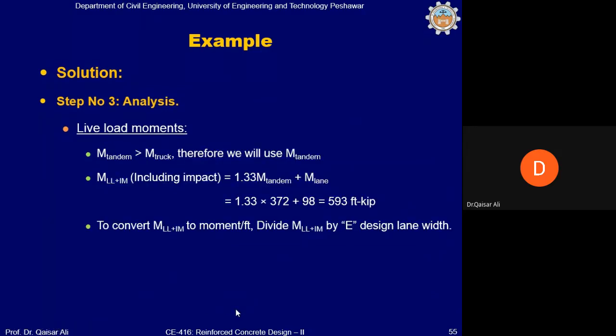We will take the maximum bending moment for the two vehicles, which is coming from the tandem. So we will use tandem bending moments instead of truck bending moments. And we will also apply a 1.33 factor to the tandem bending moments in order to include the effect of vibration or impact. So 1.33 into M tandem, 372, plus M lane, 98, gives us 593 foot kip, but for line moments. This must be divided now by E to convert this bending moment of the line to two-dimensional, in order to include the two-dimensional effects.